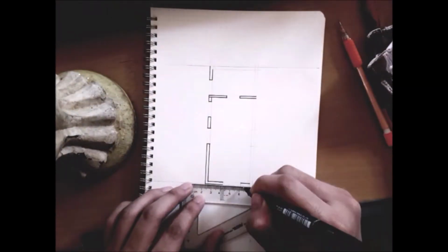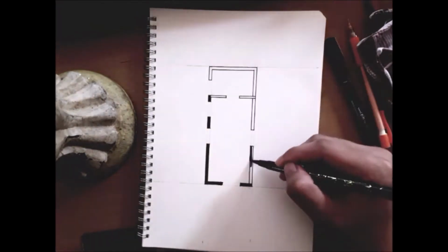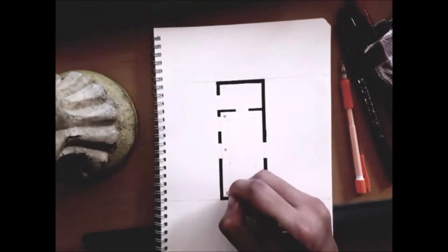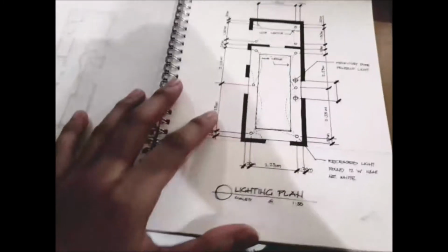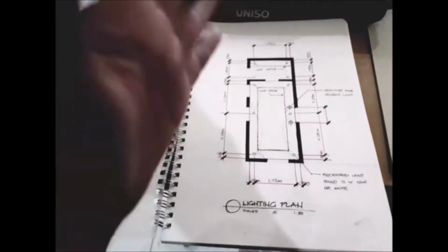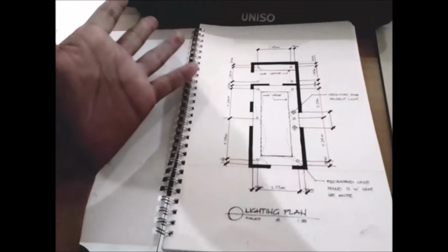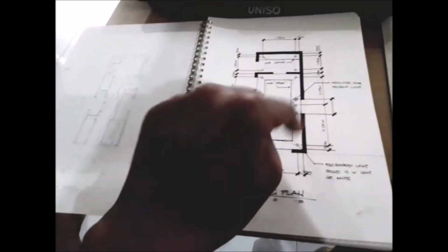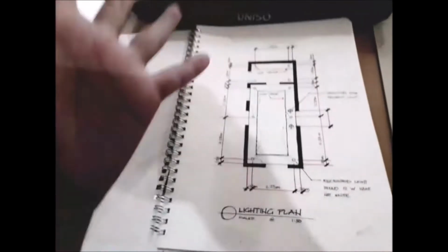After planning out the spaces, it's time to figure out where the lights would go. So what I'm doing now is the lighting plan. This plan shows what lighting fixtures you're going to use in your design and how they're going to be laid out. The lighting plan is pretty simple. I just wanted to have cove lighting for general lighting, and here are the ledges of the cove lights, and to surround those cove lights and accentuate the space, here are some recessed lights, 12 watts each, natural white.